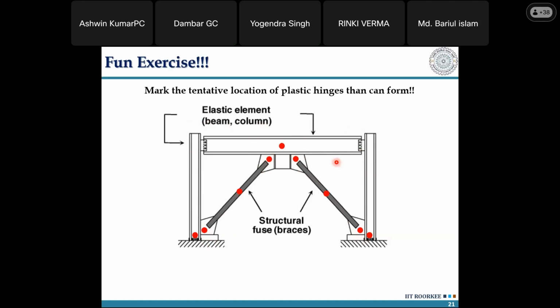You'll ask, अरे beam का size बढ़ गया तो मेरा column का size बढ़ेगा. So the question comes is, okay, strong column, weak beam criteria need not be satisfied because the ends of the beams are pinned, right? So if it is fixed and you have a chevron arrangement, then the problem is going to be increased, right?